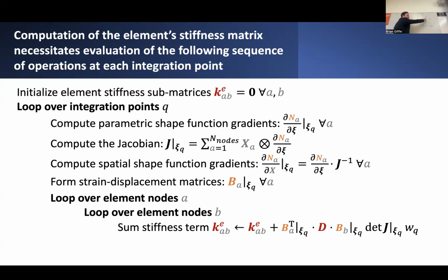If they're taking the average value of all these different integration points and presenting you with that averaged value, it might miss something happening at one of these corner points. It might actually have a more extreme value of stress that might exceed some kind of limit state that you're worried about. So just be aware of that. Knowing that there are integration points in the element is a good practical thing to bear in mind.